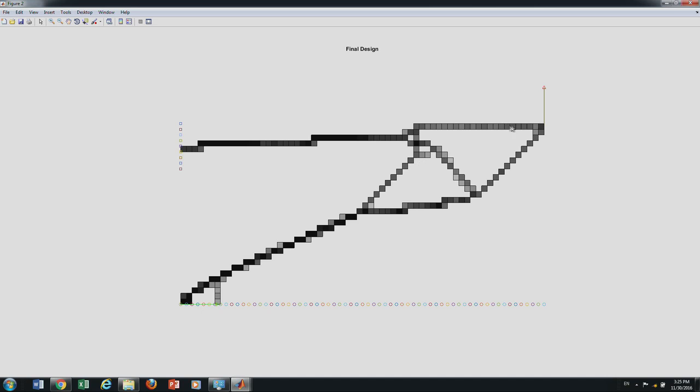So, a lot of elements are in grey color. So, black here means that rho is equal to 1, material is present. A lot of things have disappeared from our design domain here, that is all has gone to rho equal to 0. In between there are a few, giving a small volume. I will show you what volume constraint we have, then you will actually get a skeleton type of structure.